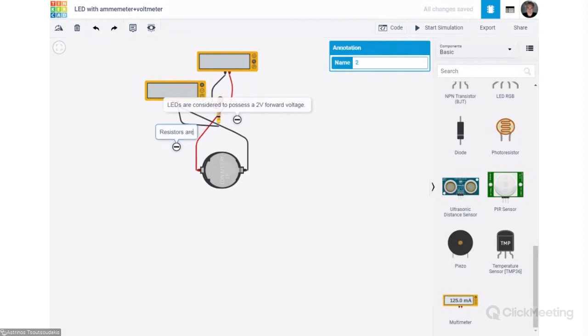resistors are tri-band. Of course, they follow the color code. As you can see, when I change the value for the resistor, the colors here change. You will find the color code in my presentation as well. And they have an extra band, which is usually silver or gold. And gold stands for 5% tolerance.